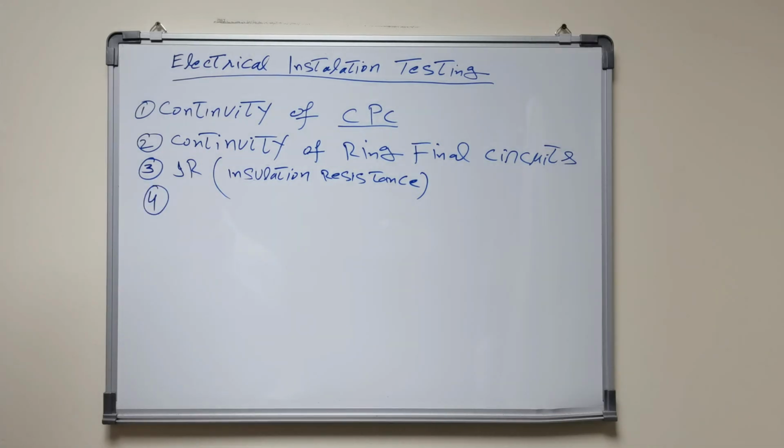For that, on all new installations we need to perform insulation resistance test before taking that installation in service.